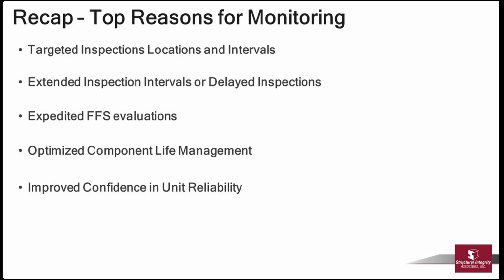So what kind of locations are you putting them in? Are you putting them in hairpin bends and economizers, or are you just putting them on pipes? In the one case that Kane mentioned, we installed some on elbows on the desuperheater drain lines that in the past were experiencing erosion.